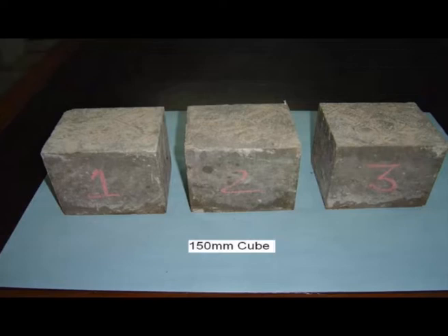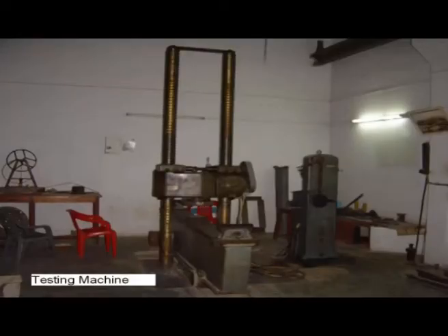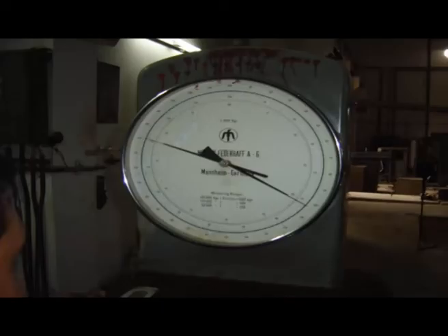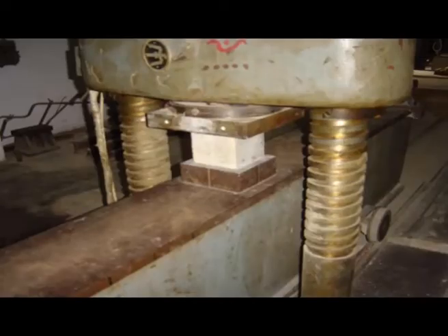Let us consider a slab made of glass from the top. Now the issue is you will not feel comfortable, since it is made of glass, it may break. Discomfort will come, you will be scared. And here also, even if you are having excessive deflection or wide cracks, there is discomfort. To avoid that at the serviceability level, you have to consider that users should not be disturbed. The limit state method defines states in which the structure is unfit. As I have told you, excessive vibration can also affect operation, so that's why we restrict things and have different limit states.